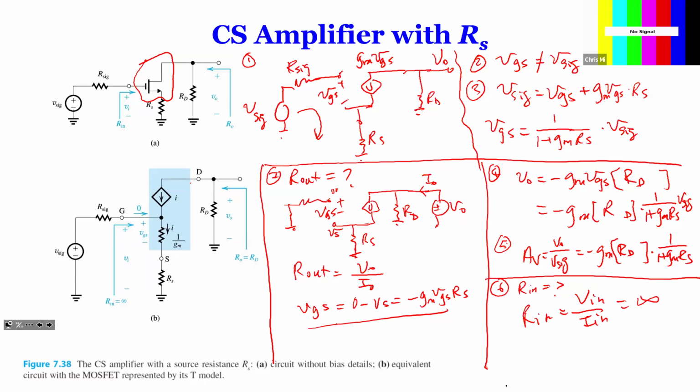You guys remember that we had a problem having this equation that wasn't quite right. So what happened is we're looking at the equivalent circuit and say, well, that's VGS equal to, because when we short the circuit over here at the input, we have VGS over here, but this is the ground. And what we're saying, there's a current flowing here, so there's a voltage drop over here. So this voltage is apparently the reverse of this voltage. And what we found was VGS equal to minus GM times VGS times RS, because this current is related to VGS.